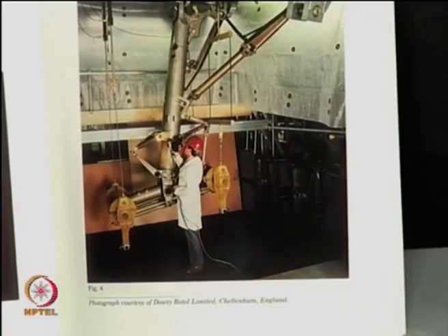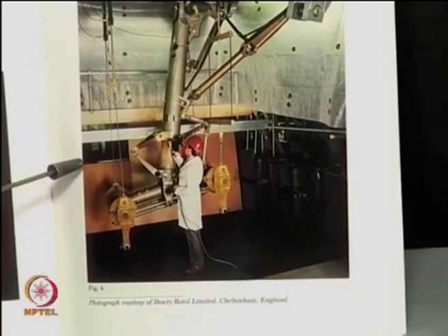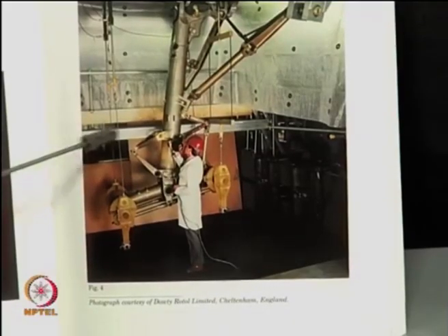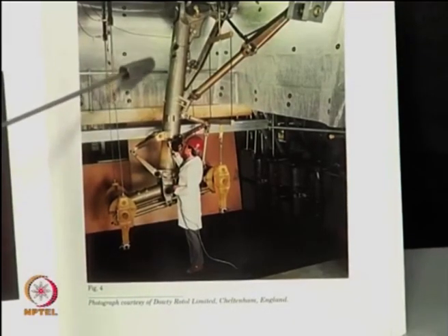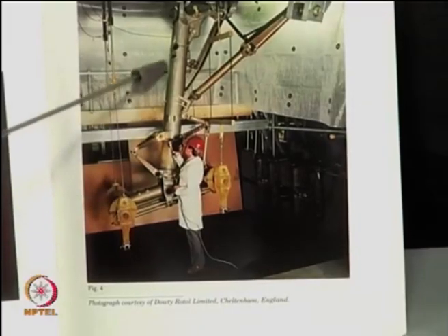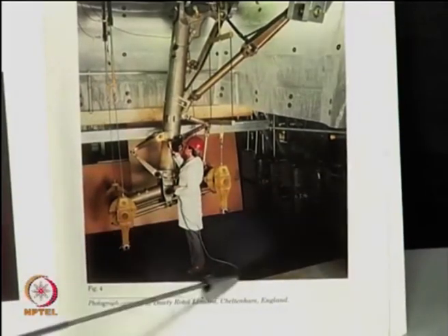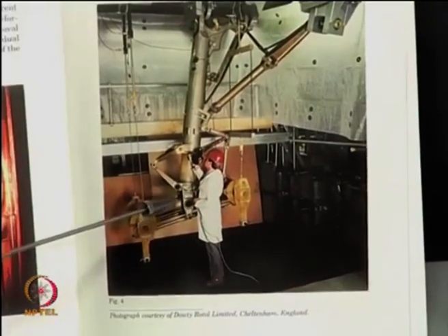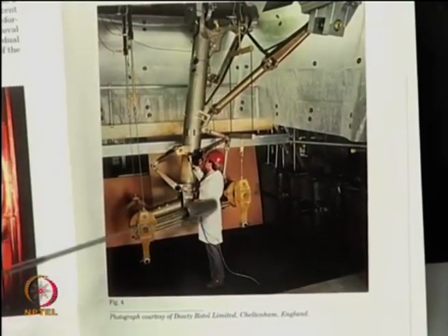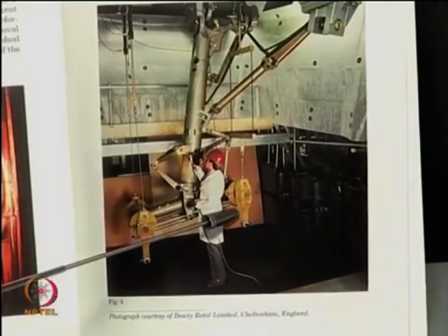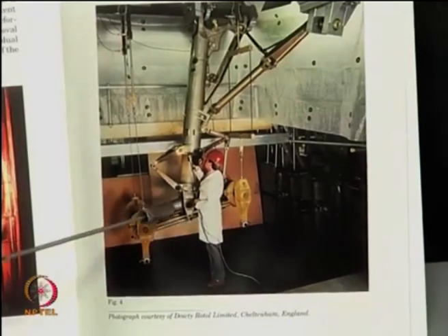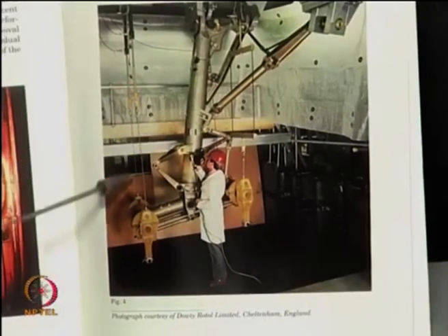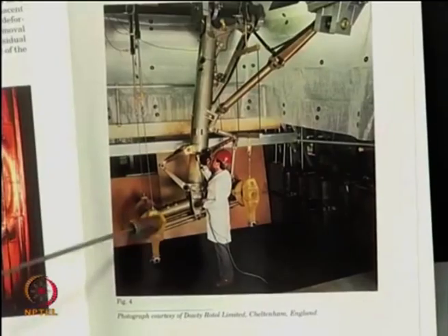This shows another example of what is the use of photoelastic coating in solving industrial problems. This is the model of a A330, A340 landing gear, and you can see the size of the model compared to the human being standing, and what is interesting is you have this as an epoxy model, that is very clearly seen from the color.